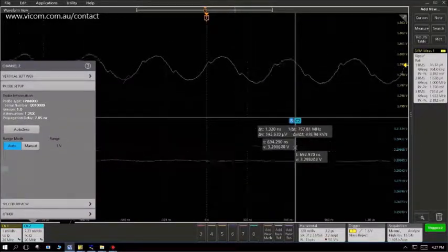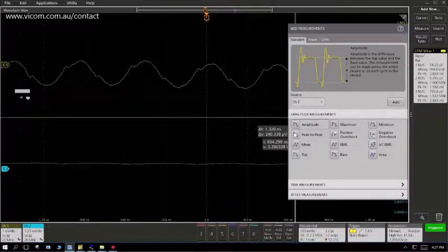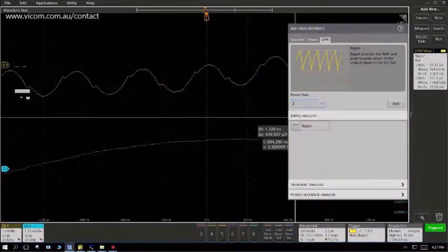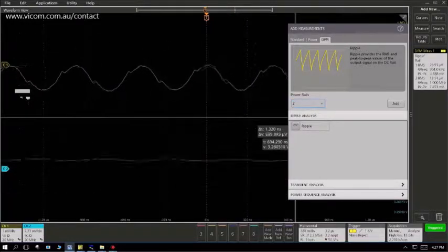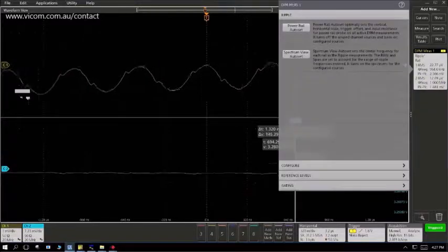The power rails are automatically identified by the oscilloscope on channel 1 and channel 2, and here we have got the digital power management software. On an MSO58 you can perform 7 power rail testing simultaneously. In this case we have added 2 power rails.